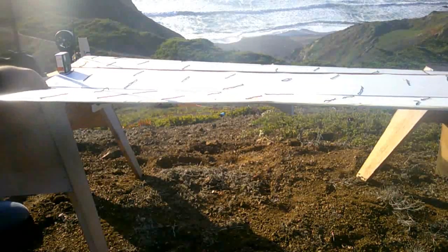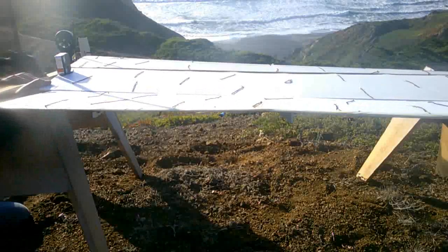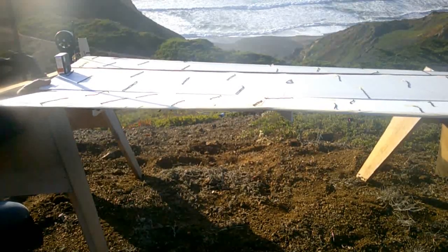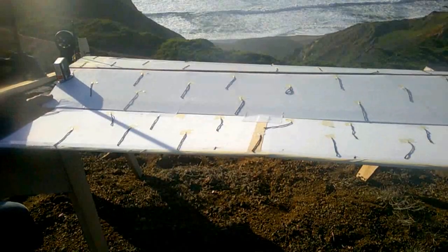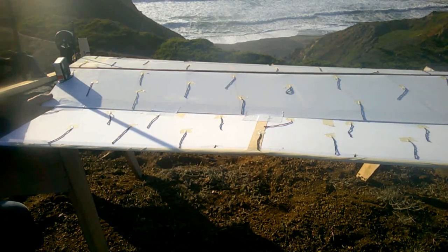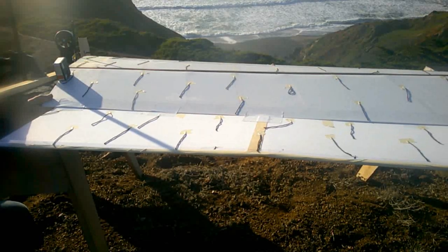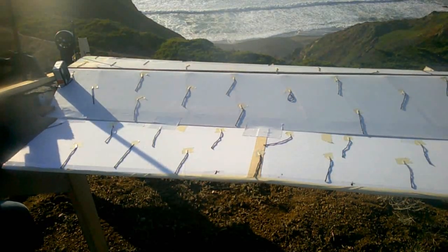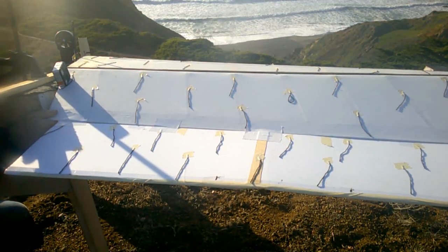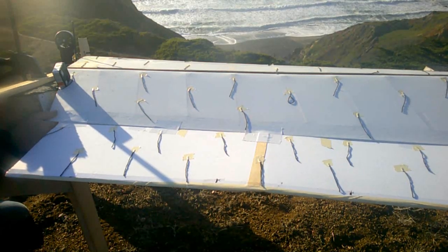So here we are rolling along, and right here I have about 0 degree angle of attack, getting set up here, and I'll bring it down to about 10 degrees down. Right there is about 10 degrees down. The wind is shifting, so we'll see the tufts move around, but they're staying attached. We're not seeing that 90-degree turn and blowing out to the wingtip or going backwards. So that's pretty well behaved flow. Then I go down to about 20 degrees. Here we are at 20 degrees down. No, this might have been about 15. 15 degrees elevon down, still attached, doing good.